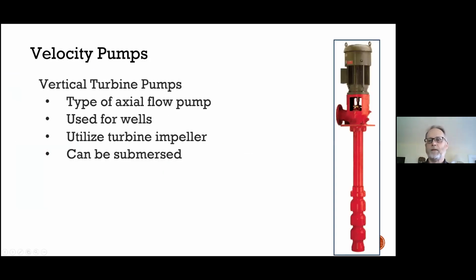So there is an impeller at every bowl here, inlet 1, 2, 3. So this would be a 3-stage turbine pump. It does both: it can bring high flow into the discharge, and it can also increase the pressure, because think about it, the impeller turns and converts the water striking the bowl or the casing from speed, kinetic energy, to pressure.